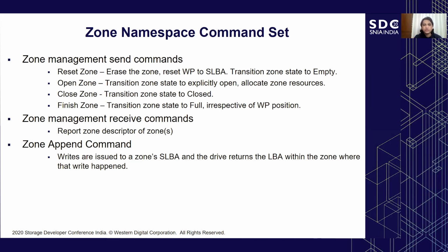And open zone command basically transitions a zone to the open state. A close zone command transitions a zone into a closed state. Finish zone transitions a zone state to full, irrespective of write position. What I'm trying to say is that when a zone becomes written entirely full, the firmware or the SSD itself moves the zone state into full.